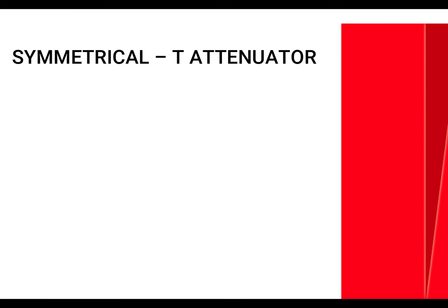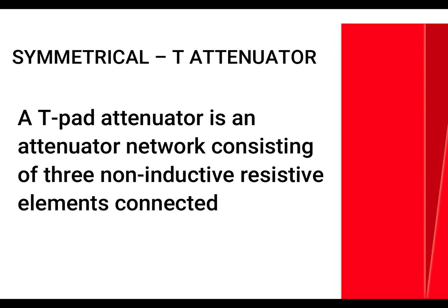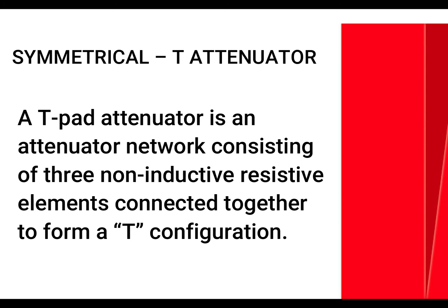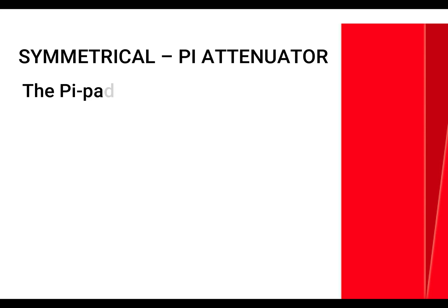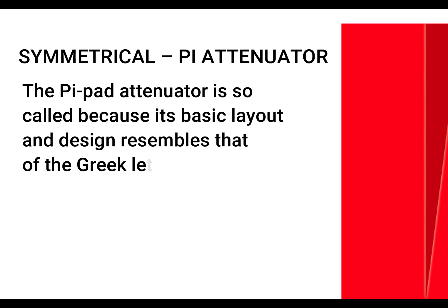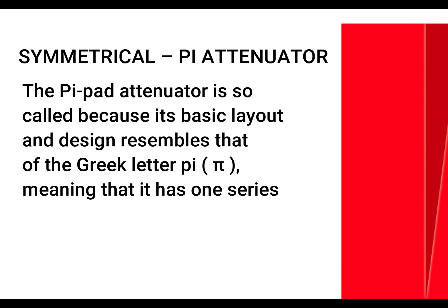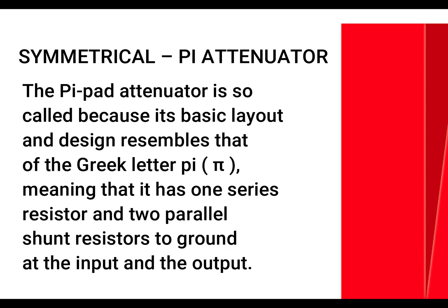Symmetrical T attenuator. A T-pad attenuator is an attenuator network consisting of three non-inductive resistive elements connected together to form a T configuration. Symmetrical pi attenuator. The pi-pad attenuator is so called because its basic layout and design resembles that of the Greek letter pi, meaning that it has one series resistor and two parallel shunt resistors to ground at the input and the output.